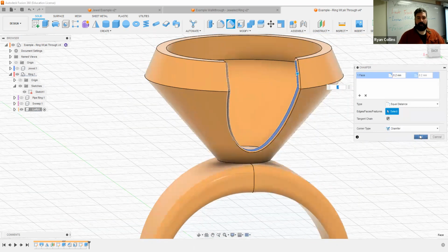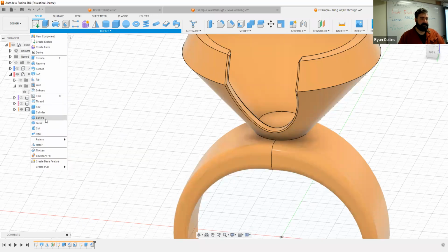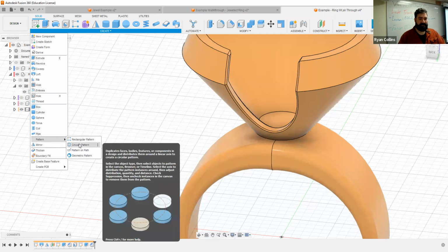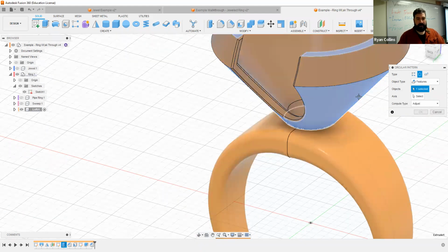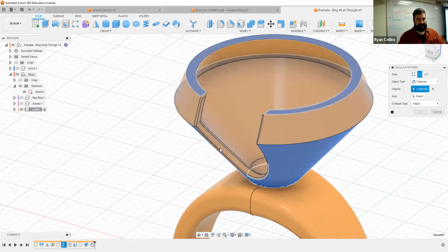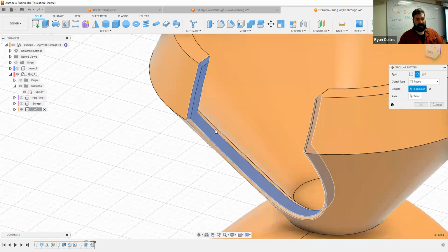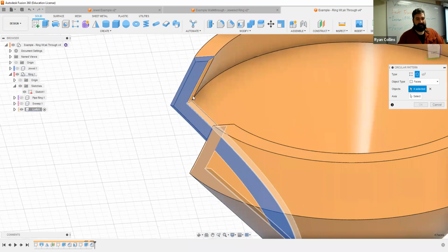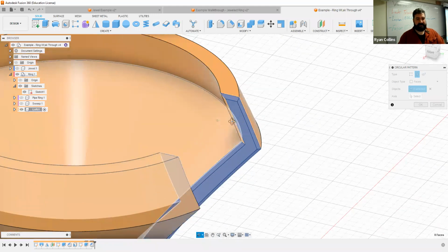Sure. Okay, that works. Now I'm going to use a pattern tool, circle pattern, to duplicate that. I'm using faces, or better yet, let's use features, because I want to get that whole feature. And if it selects too much, it's not actually selecting what I want. It's actually the exact opposite. Fine, then I do need to go back to faces, select the inside face as well as those chamfer parts. Unfortunately, that gets obnoxious when the face option doesn't select everything that you need. So just be thorough. Make sure you get all the faces I need.